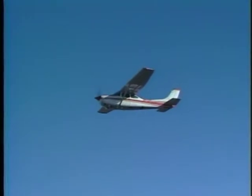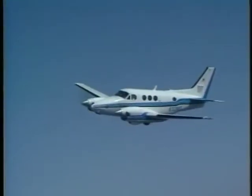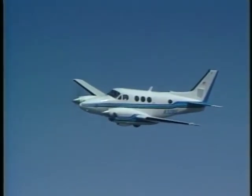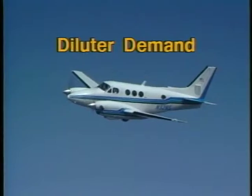Above 17,000 feet, however, you must be careful to maintain a tight seal between the mask and your face. Above 25,000 feet, you and your passengers should use some form of demand oxygen system. The diluter demand is one of these systems and is the next one we'll discuss.